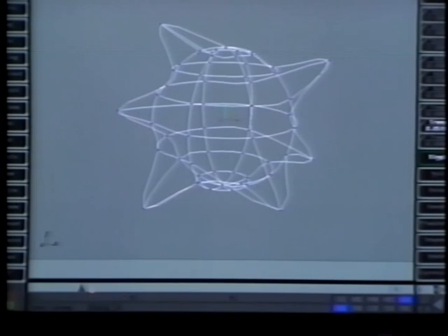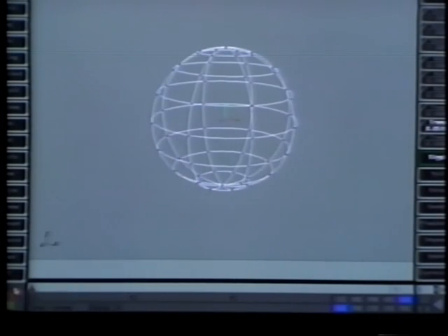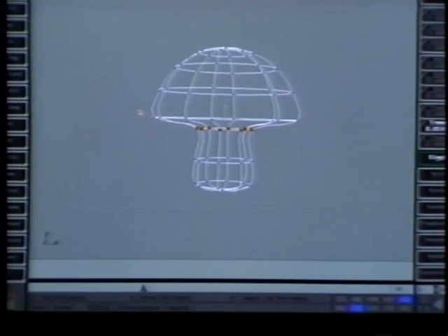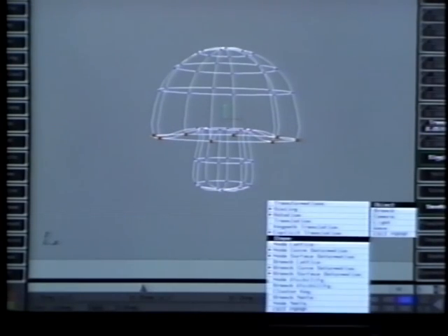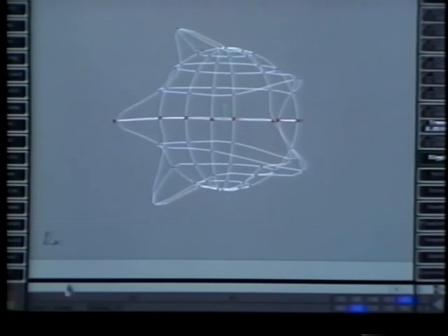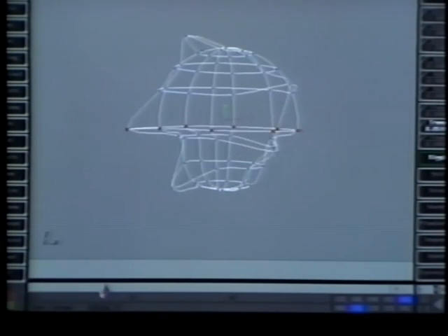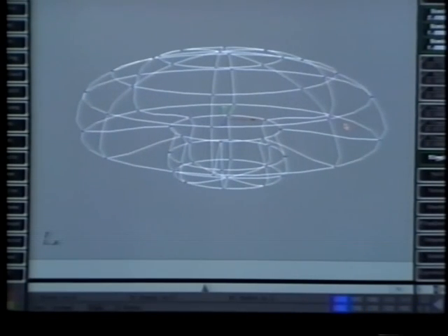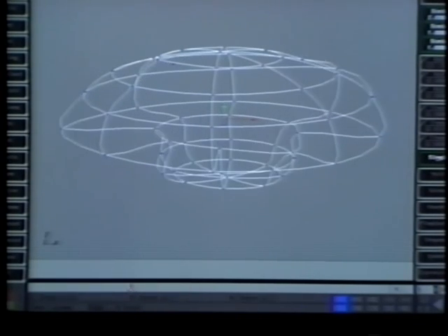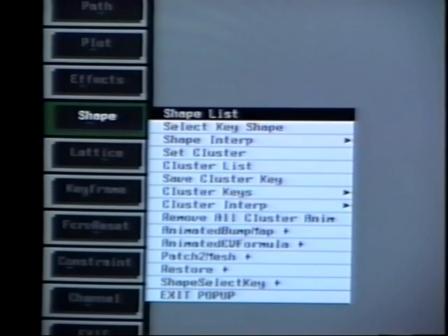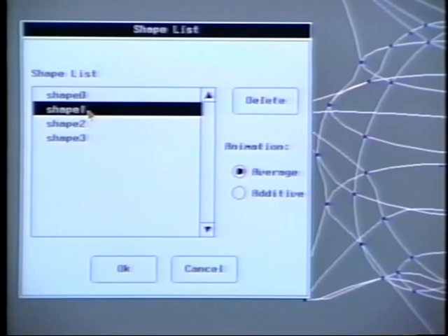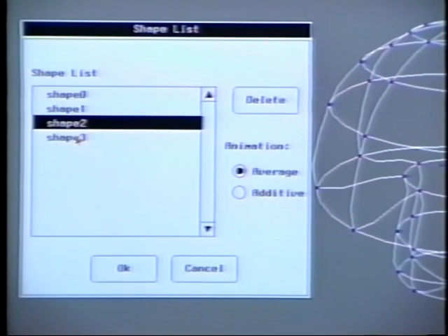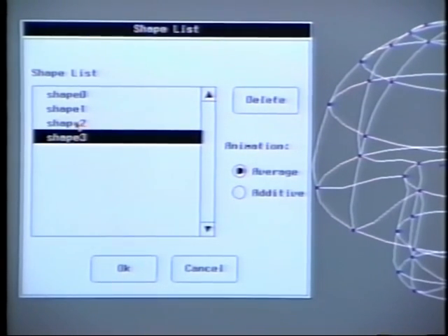When a shape animation is created, 2 types of data are being stored: your shapes themselves and the F-curves that control them. A shape is information storing a position for every point in the object relative to the object's center. Changes made at the object level, such as scaling or translating the model, are not recorded by shape animation. You can see all the individual shapes that are linked to a shape-animated object by looking at your shape list for the object. Clicking on one of the shapes will make the object show you that shape. Shapes stored while the object was scaled differently are still redundant.